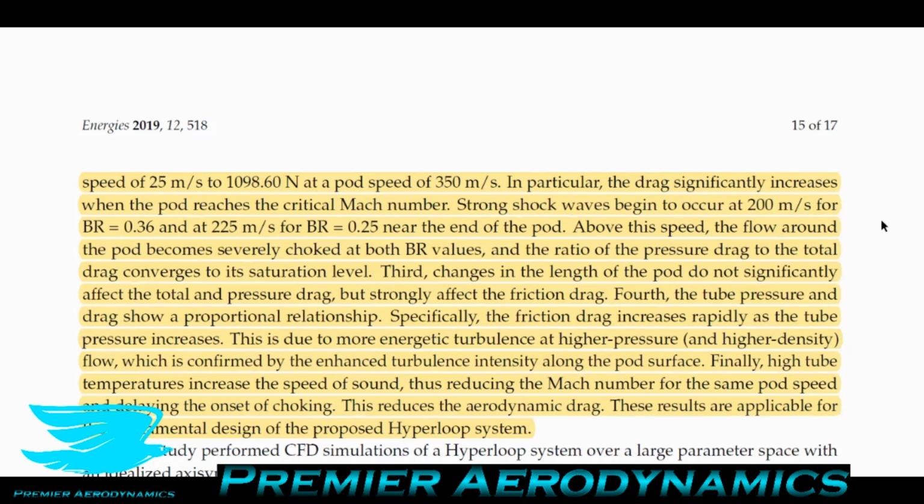And also, if you do experiments or you have CFD that you want to validate with experimental data, you need to make sure you measure the density of air, because as we've talked about throughout this paper, it does change with different atmospheric conditions. And on a regular day, it changes by 2 to 4%, and that's not even on a stormy day or anything. It's just a regular day. And between weeks and months, it changes more than that.